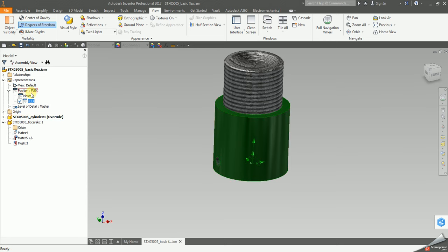So having examined the construction of the assembly that I will use as flexible, we have to use this knowledge later on. The conclusion is that this piston can only move along the axis of the cylinder, and it is constrained in such a way that it cannot be flipped upside down or rotate.